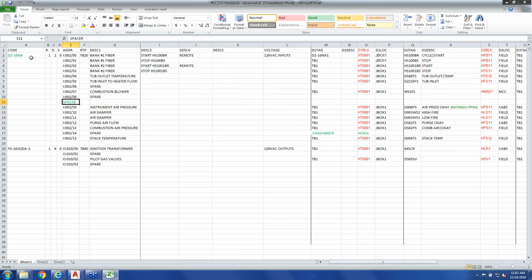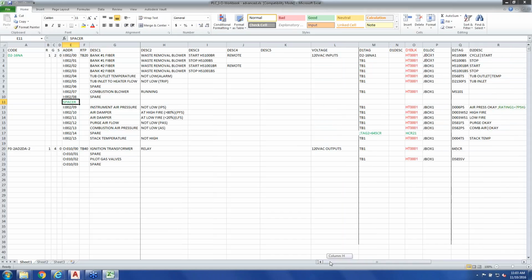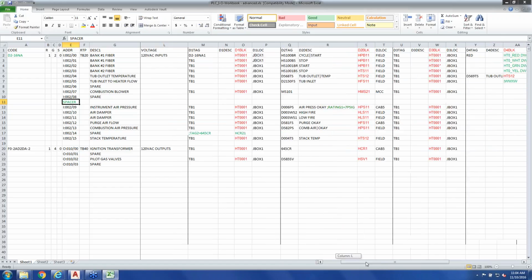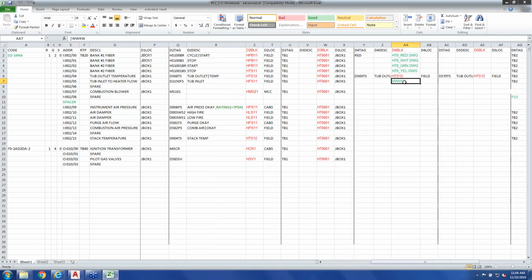over some of that. So you can see here I've still got this spreadsheet up. We have the codes for the PLCs. I've inserted an additional spacer here. I could also insert a break here instead, where it would actually break this PLC into two pieces. Some of the things that are supported within the default PLC I/O utility are adding jumpers between different lines.